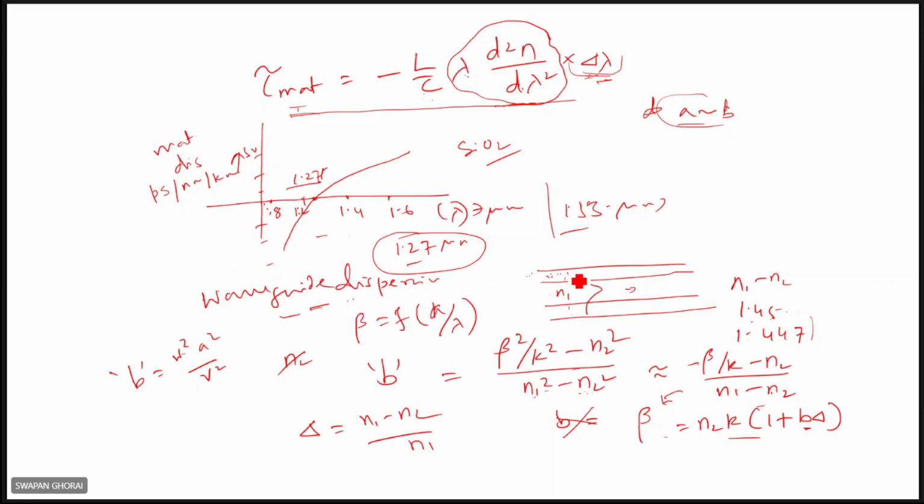What is the reason for waveguide dispersion? We have seen this when light is launched within the fiber. Certain power is carried within the core, and certain power is carried within the clad. Right. And this is, I mean, 80%, 20%. And the refractive index is different. So obviously, there will be a dispersion effect. Pulse broadening will result because of this refractive index variation. Group velocity will vary, and in that way you can have the pulse broadening.